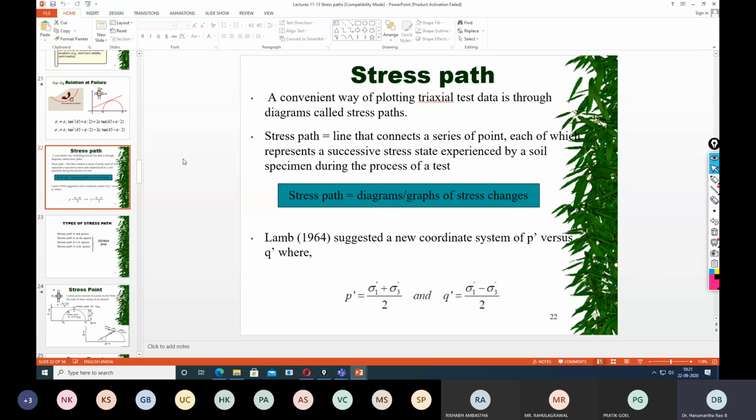Okay, but is the settlement completely zero ever since the load is applied? No, that's because if you recall your elastic settlement or the consolidation settlements, elastic settlement will happen immediately. That means because of this elastic settlement, there is a small amount of shear stress on the soil, which is much lesser than the shear strength of the soil.